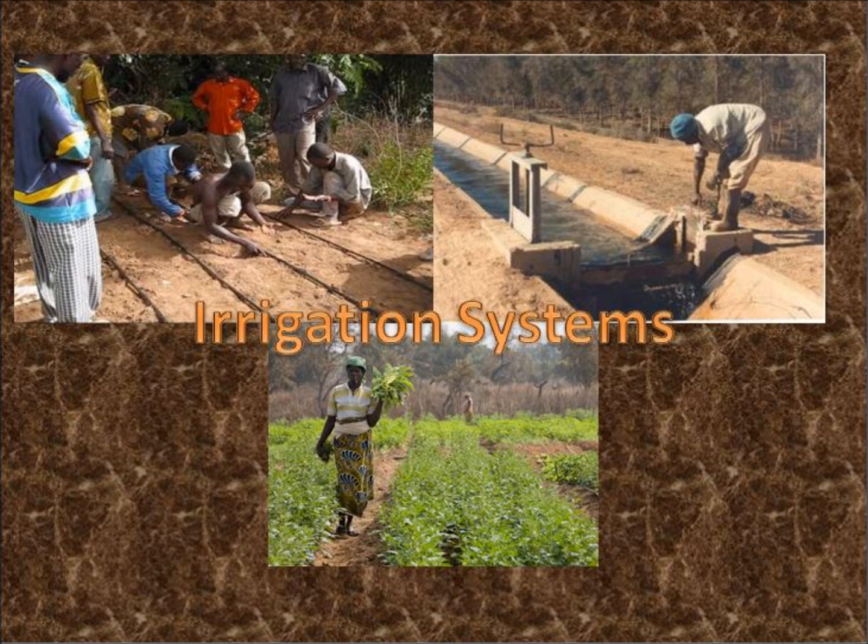One technique that has been employed in Benin, a small country in West Africa, is called drip irrigation. For this project, engineers installed solar-powered drip irrigation systems in an attempt to create a more economically feasible project. Drip irrigation is an irrigation method that saves the valuable water that people have access to by allowing it to drip slowly onto soil through a network of valves, pipes, tubing, and emitters. This technology allows better water resource management and lessens the impact of the shortage of water.